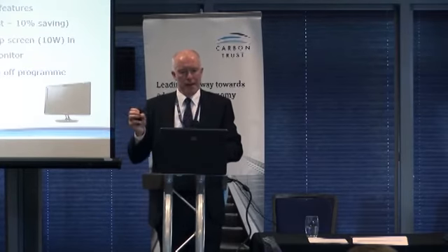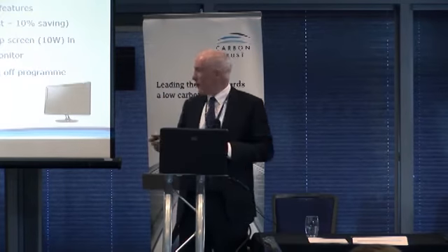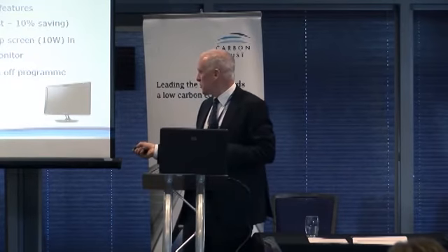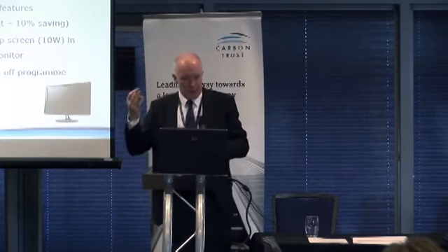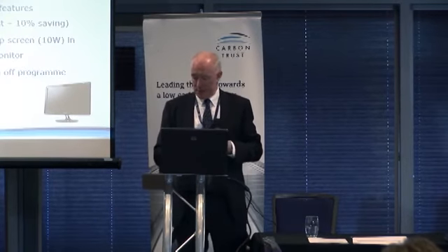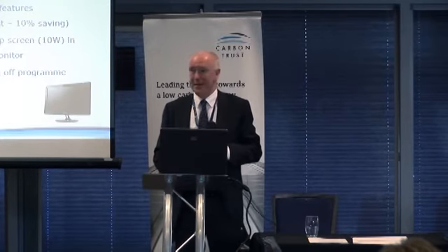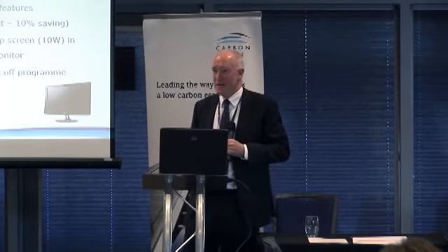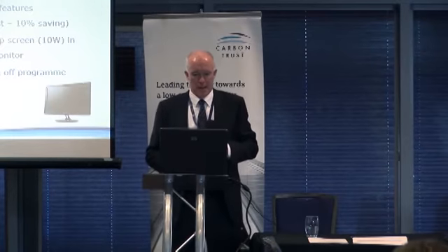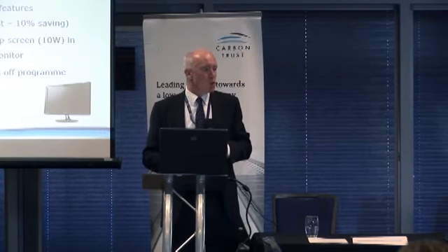In terms of monitors, we've had huge improvements. The old cathode ray tube television set, about 100 watts a piece, and we're now getting down to screens, 22-inch screens that are down at 15, 16 watts. So do look at those upgrades. I came across a company only a couple of weeks ago that had hundreds of these still in work. I don't know how amazing that they had them, but hopefully everyone's got rid of every cathode ray tube screen within their business. If you have got a screen, check the modern screens and check they've got auto brightness features.